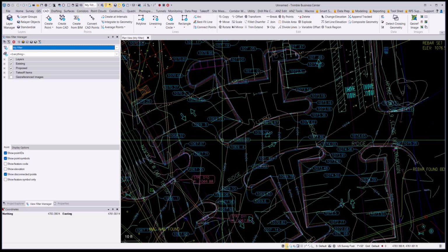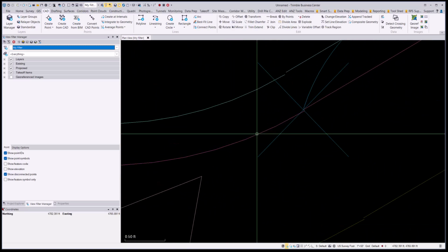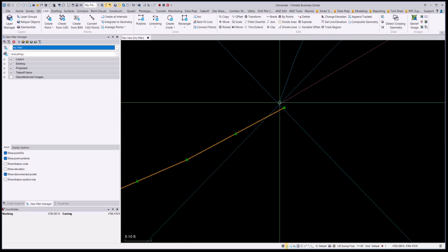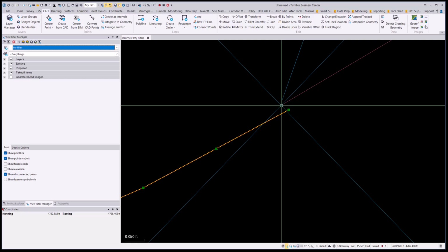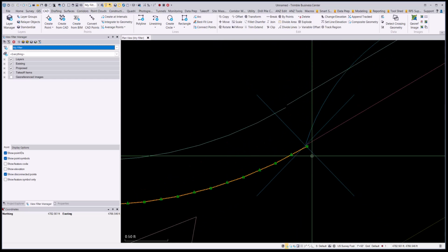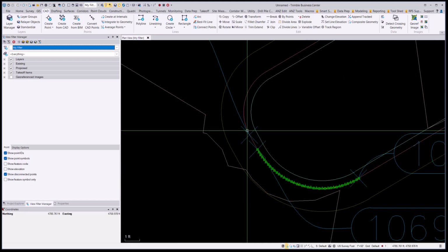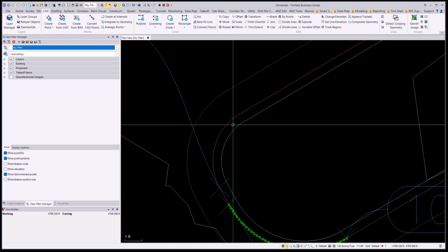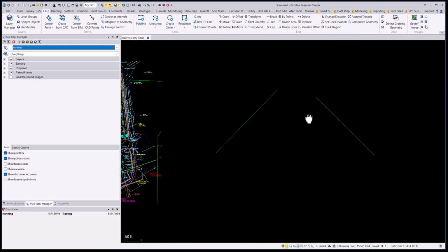One of the locations I can show you right now is on this curb face, which is a line we're going to try to isolate. Those two lines don't touch. They're not at the same endpoint. When you bring PDF vector data in, a lot of arcs get shifted, and it is hard to clean up. So we're going to talk about just some normal CAD functions.